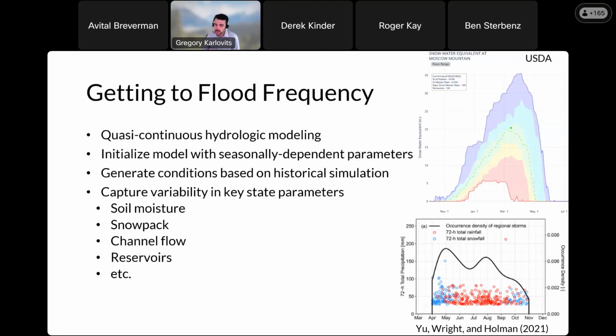types of flood mechanism. This is crucial in places especially where there are rain and snow mixtures, where there can be snow-dominated floods, rain-dominated floods, and somewhere in between. And some of those can be the worst events. Places like the state of Washington, where rain on snow is devastating. Those are places where you have to be able to model the variation of the combination of initial snowpack, initial soil moisture, and then the types of storm events that can fall on them. And so in order to do that, you do need to build a kind of complex continuous hydrologic model to capture those states accurately.